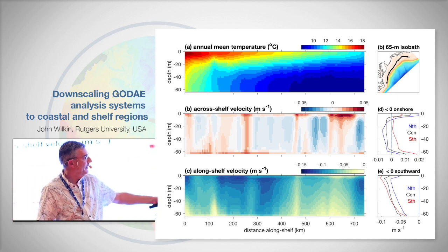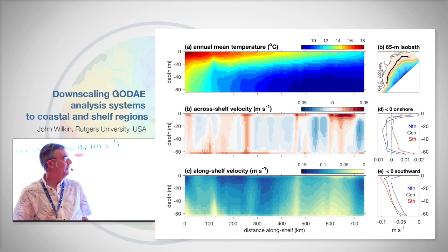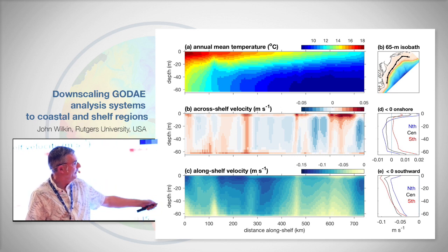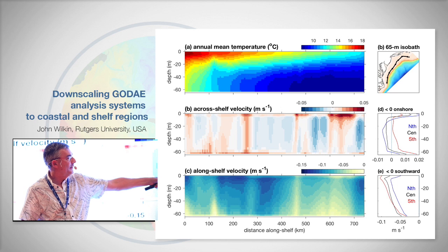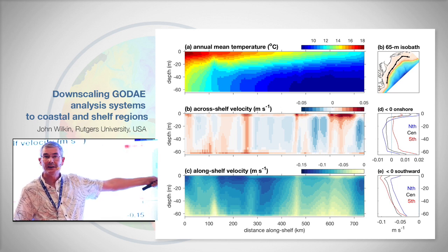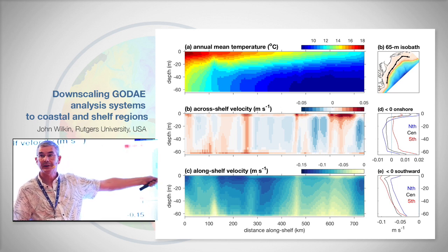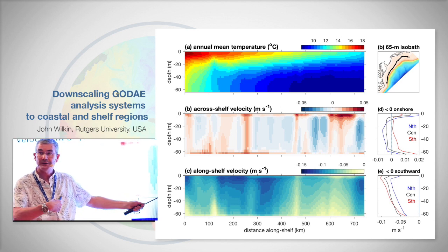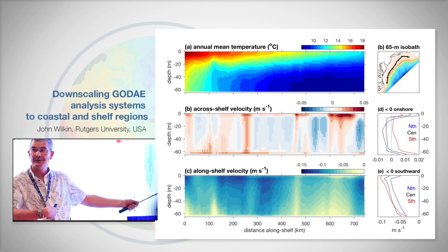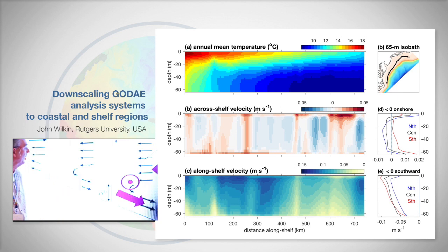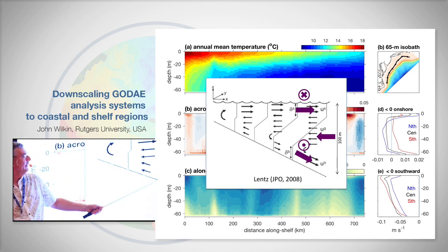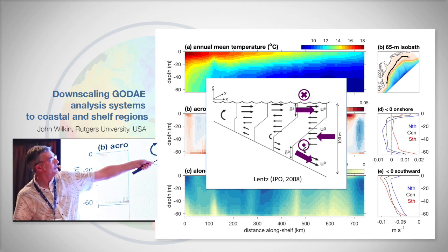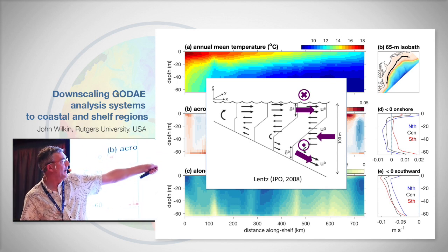And then you'll see something that agrees with a very nice analysis by Steve Lentz: there's an inflow through most of the water column, but there's offshore flow in the surface Ekman layer because the winds here are easterly, and that drives sediment transport. And since there's a long-shelf flow, there's an Ekman boundary layer at the bottom. And you have a process like this. Offshore flow here, offshore flow at the bottom. This is the sense of the wind into the page.